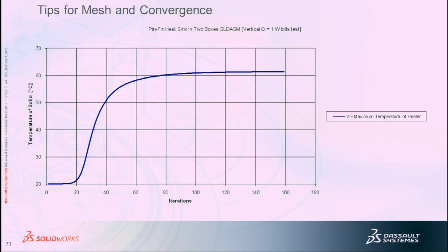Say a certain velocity, I don't know the specifics, but there might be a relationship between the inlet velocity and how many particles accumulate. So you could do a what-if study with different velocities, track how many particles accumulate for each one, and if you see a correlation, then maybe you can do a parametric study on the velocity. That's one example I can think of. Okay, thank you.